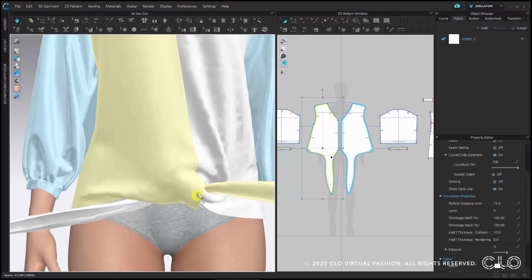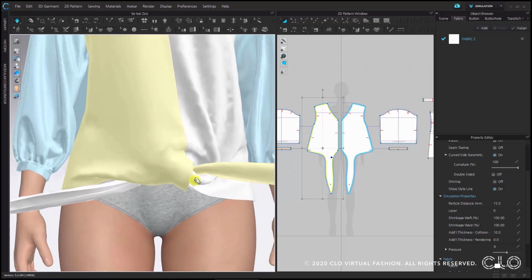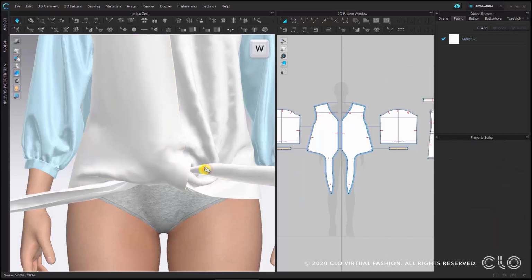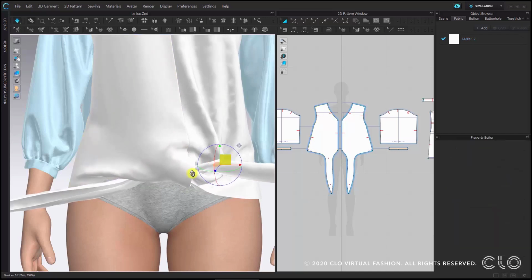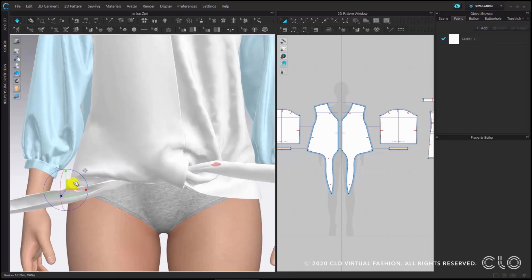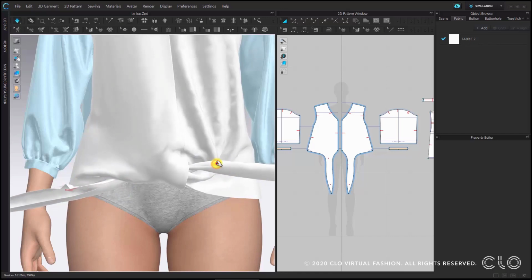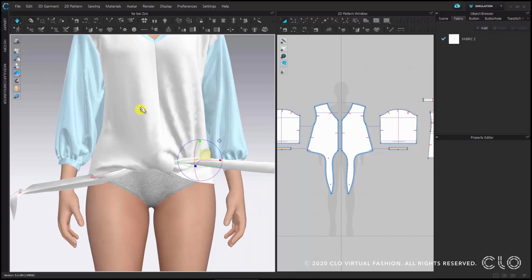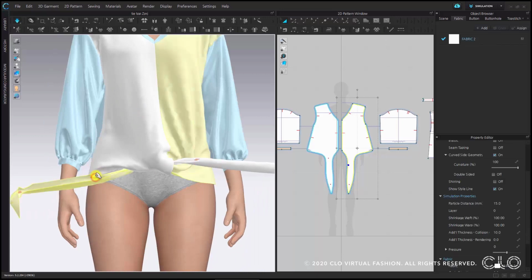When you zoom in a bit more closely and you already have a good result, you can make it even more tight-knit by adding pins to the sides. So once again, if you press W and keep it pressed down, you can click on a pattern piece and create a pin, and you see that you can always pull a bit more. We have a collision value set to 1, so there's little chance that they will, so to say, interfere.